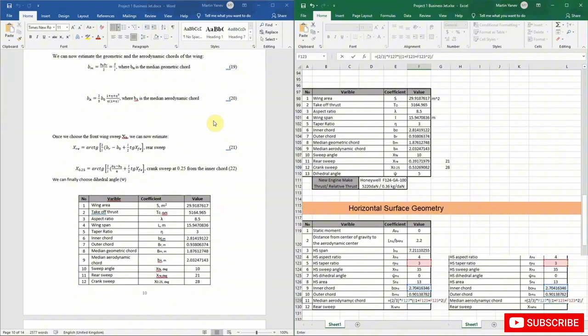It is the same logic here, and this will be divided by ni multiplied by, in brackets, 1 plus ni, and then we close all the brackets, and that should be it. So we're getting about 1.95 for our median aerodynamic chord.